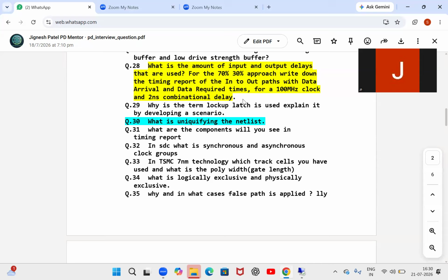Okay, good. Anything else? The start points are clocked by the same clock, and clock to Q delay also. Yes, correct. Logic level, start point clock, end point clock, logic level. Even if you use the crosstalk switch, you will see the crosstalk as well. Okay, perfect. So that you are able to mention.